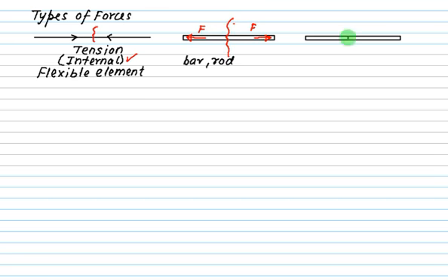So a zero force member will be represented like this. This is called zero force. These are the dummy members normally used in the case of a truss, because if any adjacent member fails, then the load is taken by this member. But up to that time, there is no force in this member. So additional members are always provided for a rigid structure.